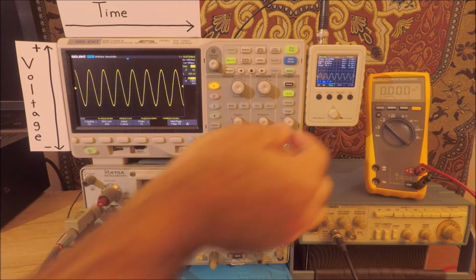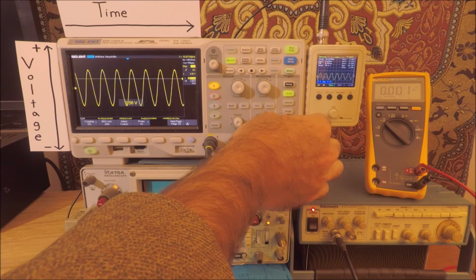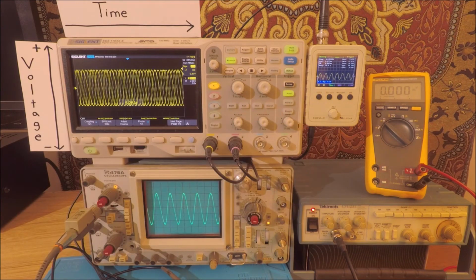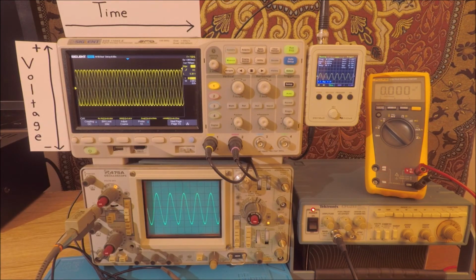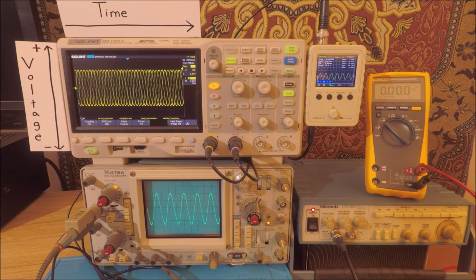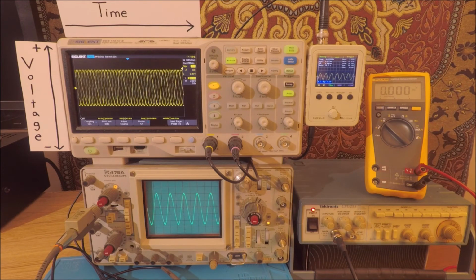Now, of course, if we move that threshold beyond where the waveform is, right here, then we'll get something like this. We can't really see what's going on right now because we don't have a proper trigger where we can view a stationary cycle or a few cycles of the waveform on our screen. So if you ever go and try to connect to your oscilloscope and you see something like this on the screen, you should immediately think that, okay, the next thing to do is to adjust my triggering so that I can have a stationary view of this continuous waveform.